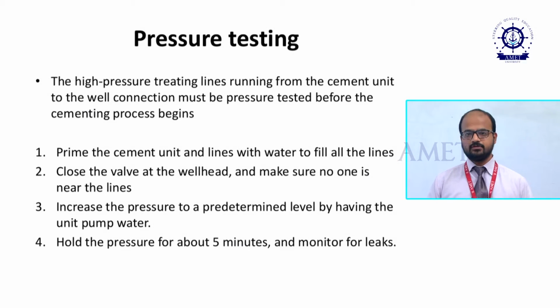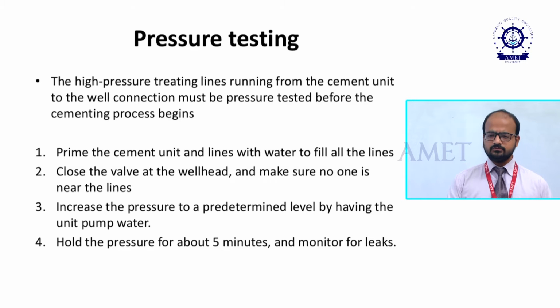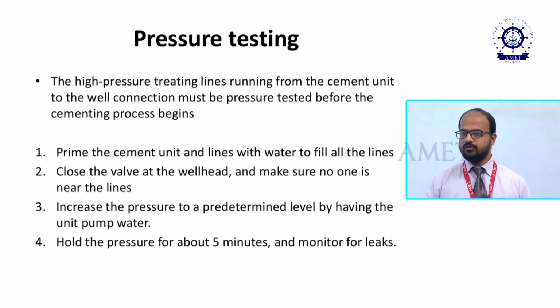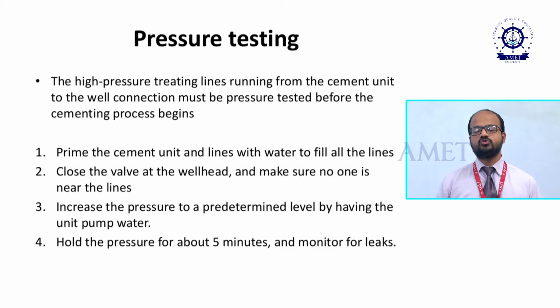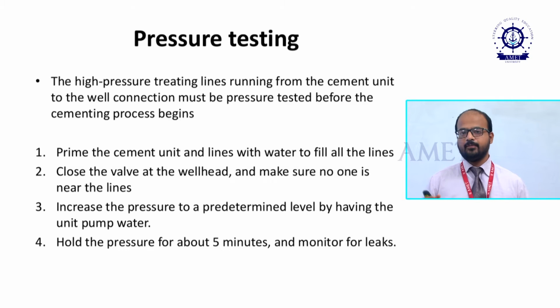Now we are going to test the pressure. First we have done the casing, then our well is completely filled with the mud. Everything is now ready. Now we are going to test the pressure, which means whatever surface equipment we are going to pump the cementing with, before that we have to check whether any leak exists in the surface flow lines. For that, we have to fill all flow lines, storage tanks, pumps, everything with water, and I have to increase the pressure slowly and hold it up to 5 minutes.